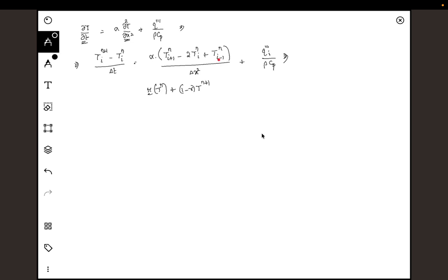So once you have this set of equations, the main idea in all these numerical methods is first you have a PDE, the governing equation. Once you have the PDE, you first discretize your domain, so basically convert your continuous domain into a discrete domain. Inside the discrete domain, you take the same governing equation, but now it applies at each and every individual point. So each point will essentially have to satisfy the governing equation. Every discrete point will now be one equation.